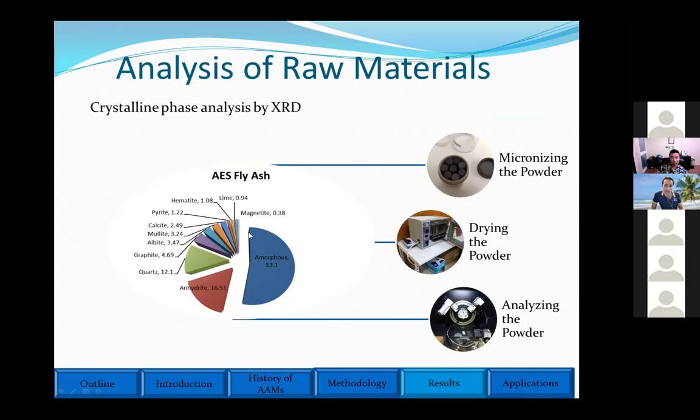If we want to dissolve it well, we need to introduce chemicals with higher concentration or weight for some bad components of this waste material, for example calcite or sulfate, because these absorb the water of the mix, and we couldn't further the mixing procedure of the alkali activation.